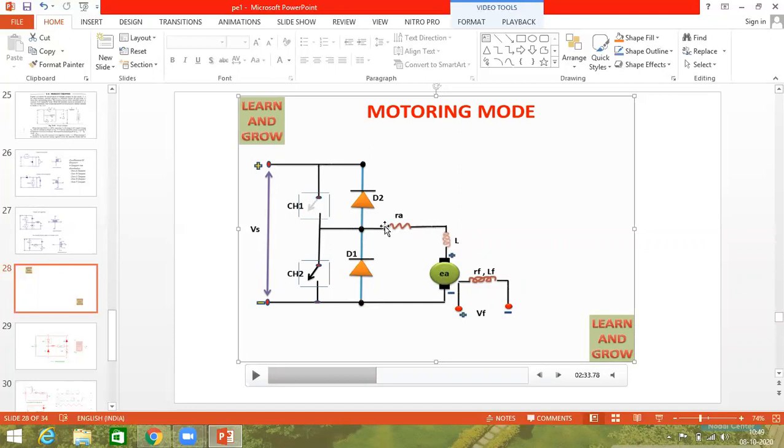RA you can also mention. So what is the direction of the current again in case 1? L plus to motor. Here the condition is that the inductor voltage is greater than the back EMF. That's why energy is traveling from the inductor to the motor. So L plus to motor to the freewheeling diode, and from the diode again to L minus. Understood now? What is case 1?